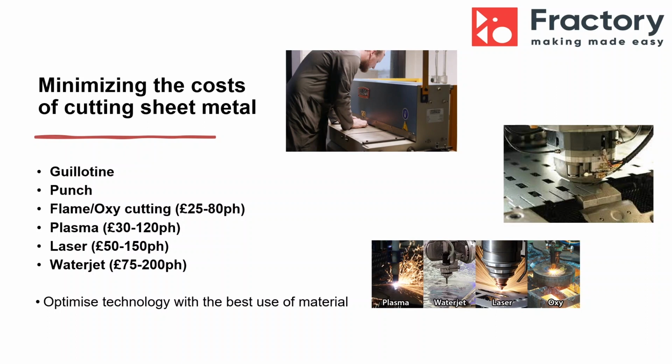The punches, as you can see in the middle image here, that's custom tooling which punches through the sheet metal to actually cut out features such as squares in this image, but also holes or anything you want really, as long as you can stomach the cost of getting the tooling made in the first place. So with that being said, again, not really too practical for your smaller production runs, but when you've got higher volume, it does come into play and really does save time.